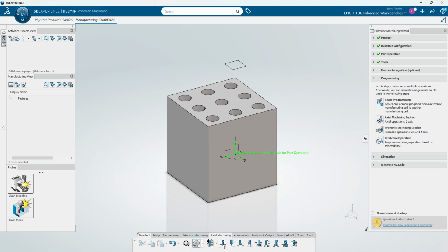But I guess I kind of run through them quickly. Obviously drilling is going to put a hole. There's a couple types of drilling. So drilling with a dwell delay, so letting the drill sit for a second to probably clear up the bottom of that hole. Drilling to break chips, so peck drilling, so that you make sure that you get those chips cleared out. Because if you just drill straight through and the chip loads too much, you can actually end up getting your drill stuck or breaking it in the part, and then you probably have to scrap the part.